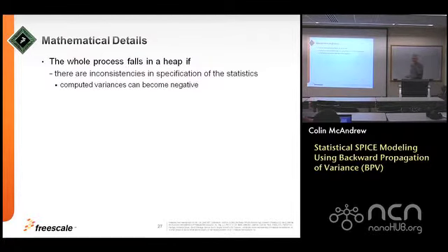So the first is if there are inconsistencies in the variations that you put in. If you remember the example with the variances where I had a variance of a beta and I'm subtracting off basically the variance of the TOX from that. Now if I look at a wide long device, they're essentially 1-to-1. When I look at the variance of the peak GM of a wide long transistor, it's in a relative sense, it has 2 sources, the TOX variation and the mobility variation. And I add variances. Therefore, the variation in the peak GM must be greater than the variation in the oxide thickness.